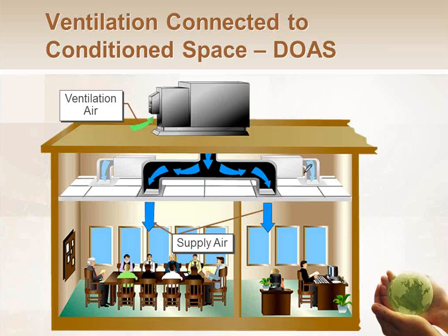So one way is to duct it directly to the space. I'm not a fan of this way. You would still have your air handlers and fan coils or rooftops or whatever bringing conditioned air into the space. And then the ERV would semi-condition the air and dump it into the space, and I would be relying on the space to be where the mixing happens. On a very cold day, I might be dumping 50 degrees here, and this unit over here is doing 90, and then I'm mixing them in the space. It tends not to be the most comfortable scenario for people. So this is not the best way to do it.